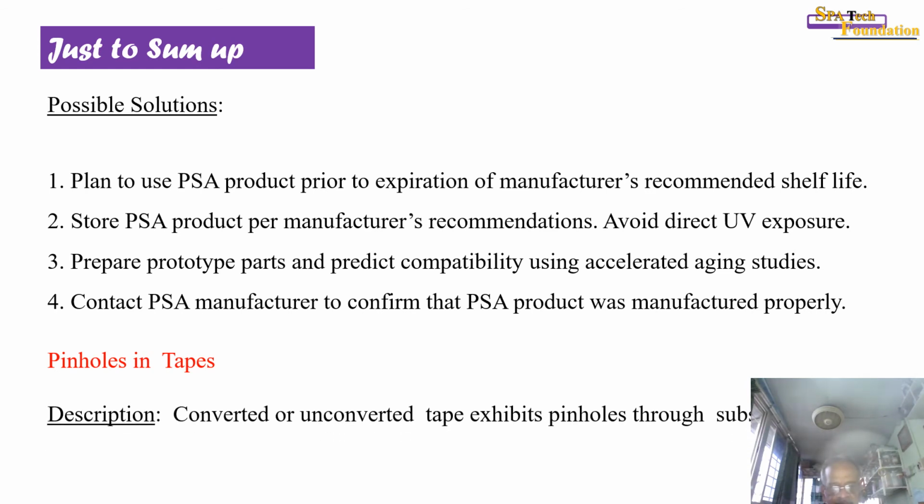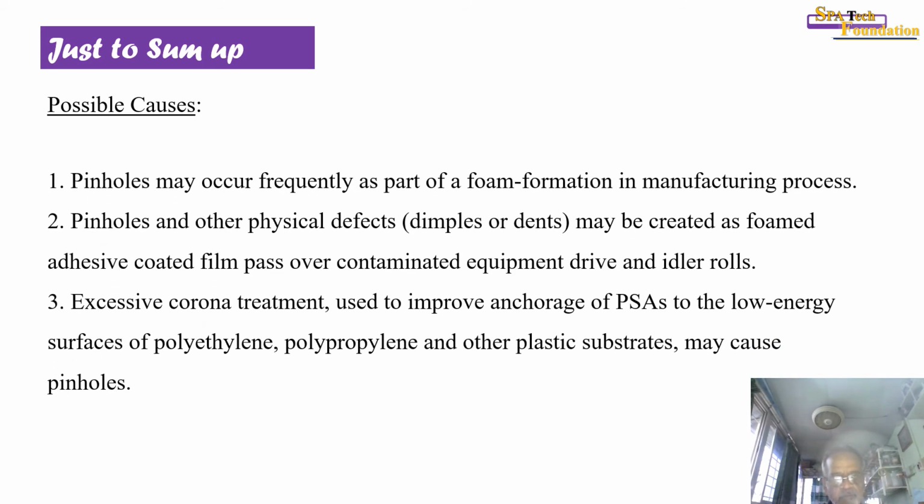Pinholes in tape. Description: converted or unconverted tape exhibits pinholes through substrate. Possible causes: pinholes may occur frequently as part of a foam formation in manufacturing process. Pinholes and other physical defects may be created as foam adhesive coated film passes over contaminated equipment drive and idler rolls.